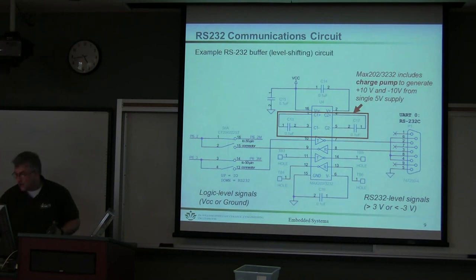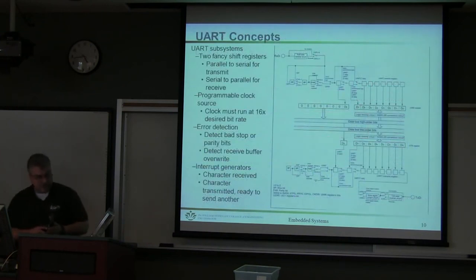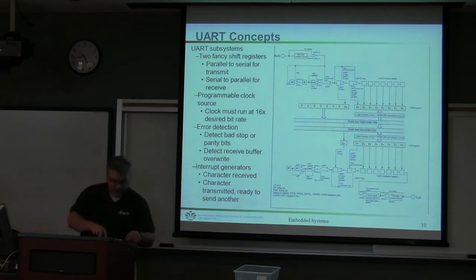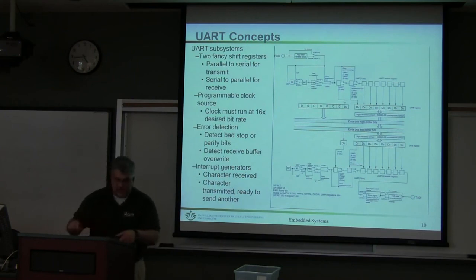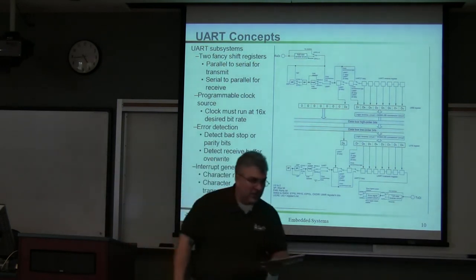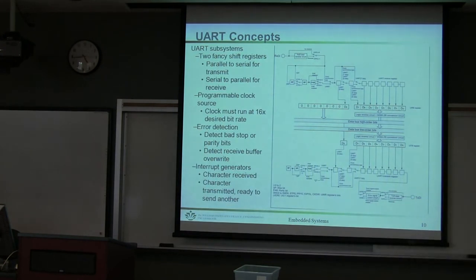By the way, this charge pump generates plus 10 volts and minus 10 volts from a single 5 volt supply in an old board. And this new board, I'm not sure how much it is. That might be a good example of something for you guys to actually measure, so I may add that into the lab. Have you actually measured the voltage using a logic analyzer? How many of you have actually used the logic analyzer? Or the oscilloscope, we'll have you look at that too, to see if you can see data coming across, and also how much the voltage is.